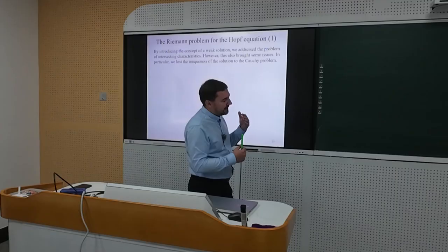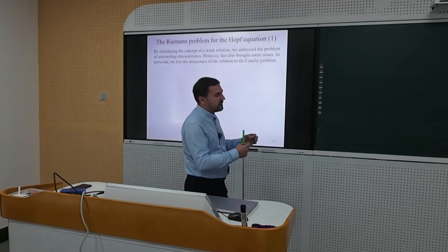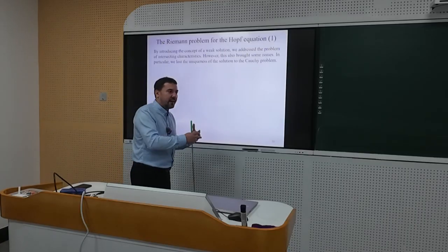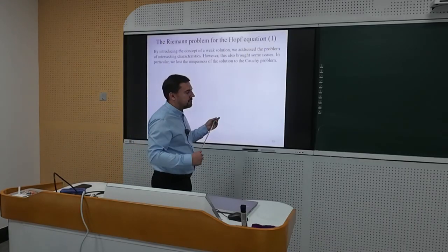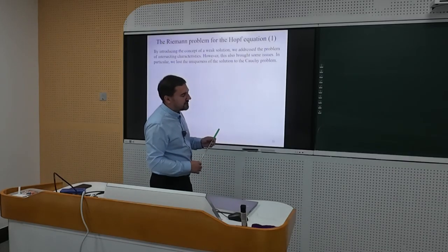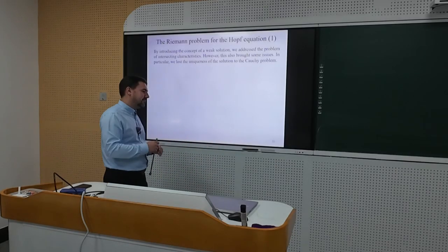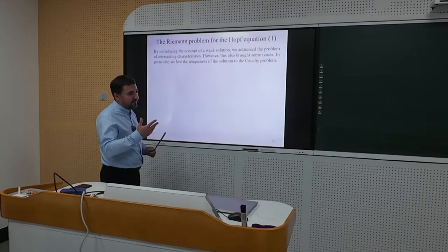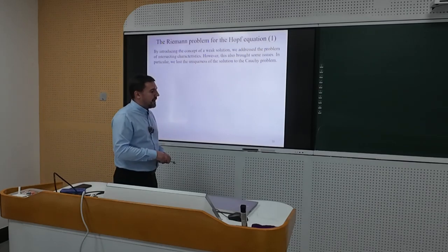And finite volume methods rely on some numerical flux function. And a numerical flux function is one or another approximation of the exact flux, for example the Godunov flux.